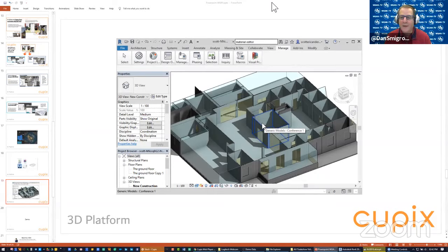Paul, you want to add something on how accurate? Well, no, I think Scott hit it on the head. If I was going out and measuring this, I would take an X and a Y, thinking of just a 2D sense. I would take the X and Y dimension with maybe a laser measure. But that, let's say, could be 10 feet on one side of the room, could be 10'2" on the other side of the room. So that's what Scott was implying, that every building has that aspect.